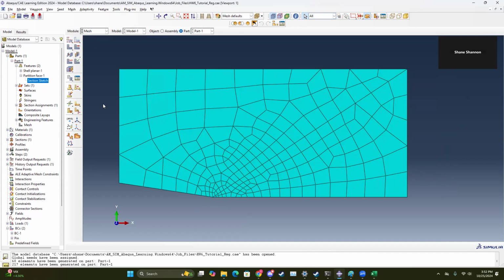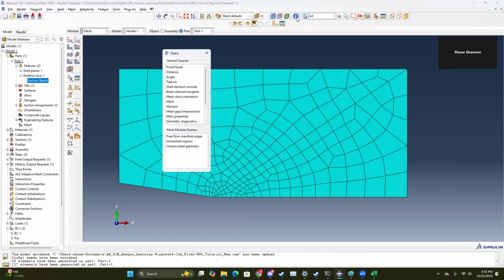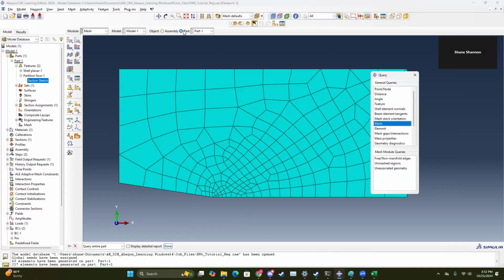And to double check that we're doing a-okay with our mesh, it's all underneath that 1,000 nodes. For reporting purposes, when it comes to the actual question in the report, you can go to the query information and ask about the mesh itself. Make sure that up here, the part is actually selected, entire part. You can see right here, we have 230 nodes, number of elements 217, and it mentions the type of elements going on, and that's everything.